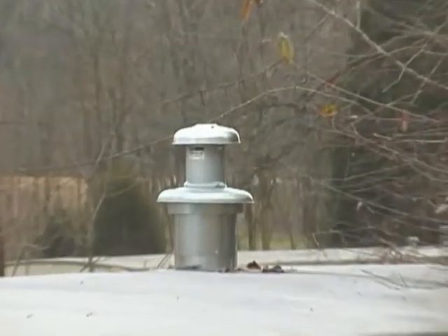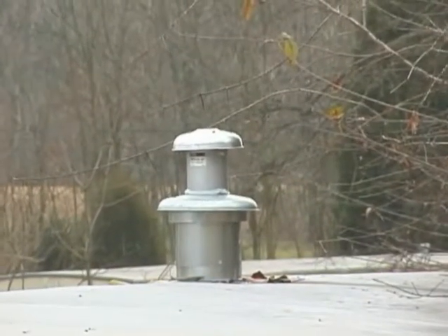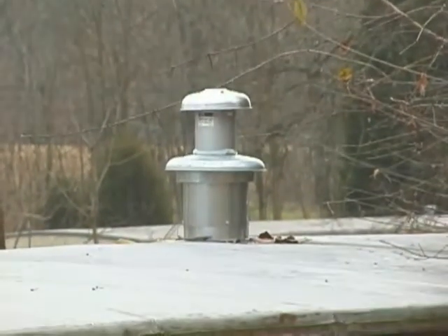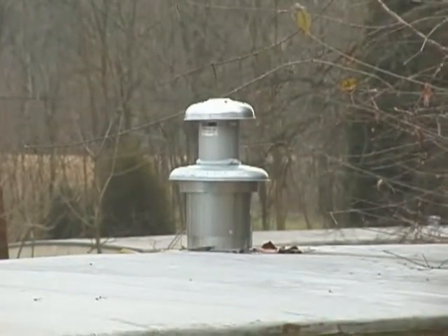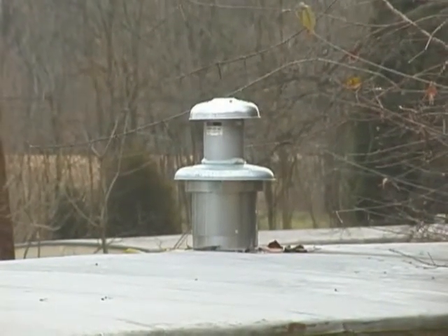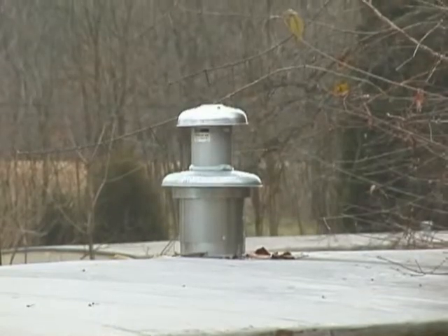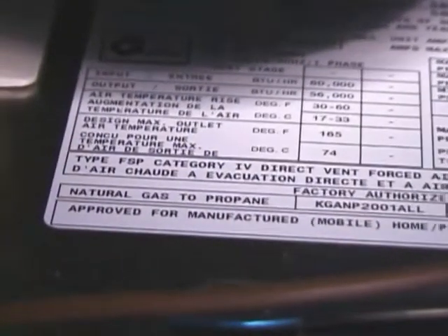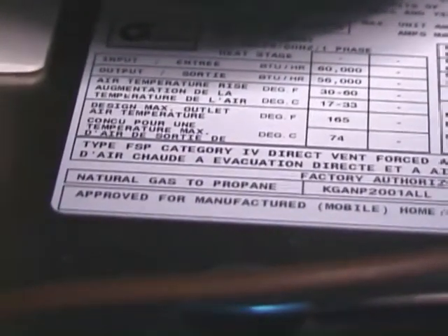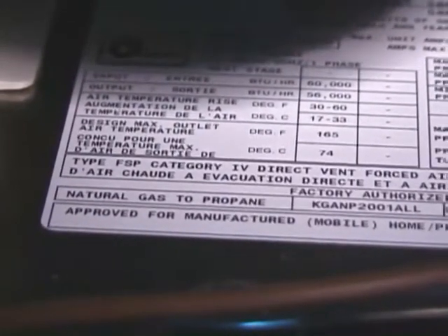The roof cap has a separate lower opening that allows combustion air to be drawn in through the outer space between the 2 pipes and is even preheated by the heat from the combustion products passing through the inner pipe. All combustion heating appliances in mobile homes must be rated for use in a mobile home and be of the sealed combustion type.